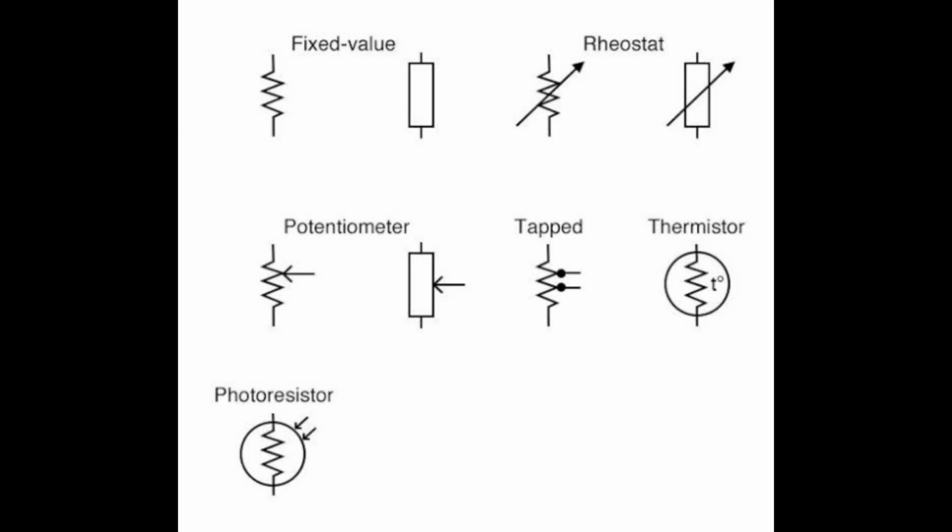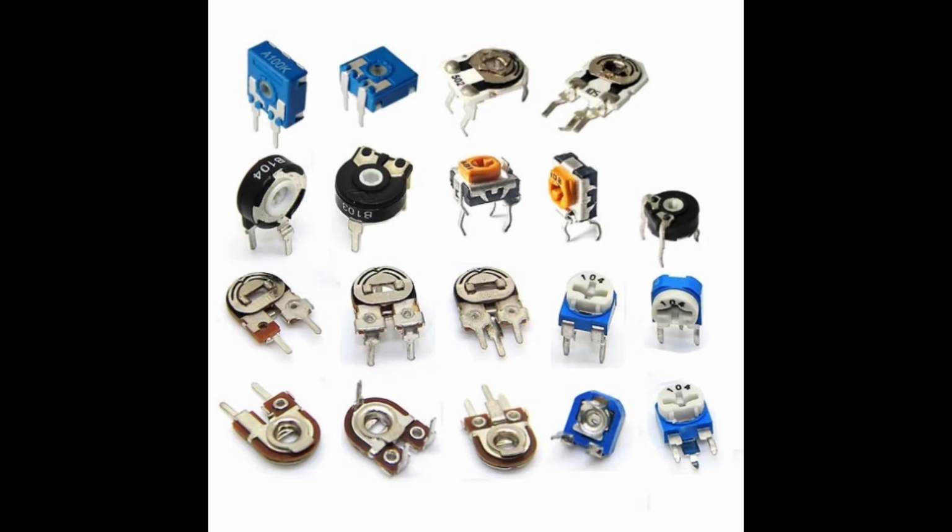These resistors are used for different types of applications depending on their power, voltage, stability, and cost. For example, carbon composition based resistors are used for transient protection. Metal film type resistors are used for audio and instrumentation circuits. Wirewound and metal oxide in high voltage body styles are used for high voltage applications, and precision circuits require trimmers and controls. This was all about resistors and their types.